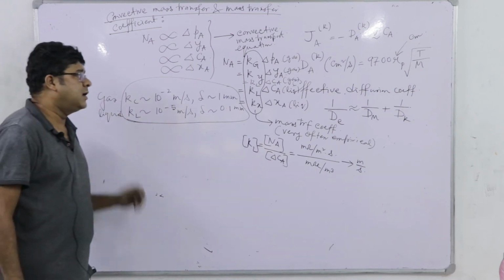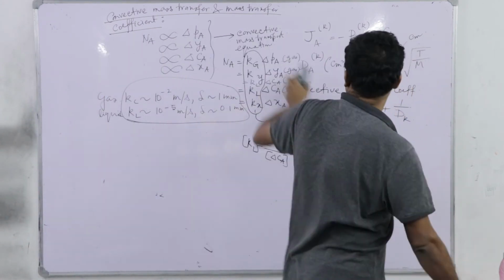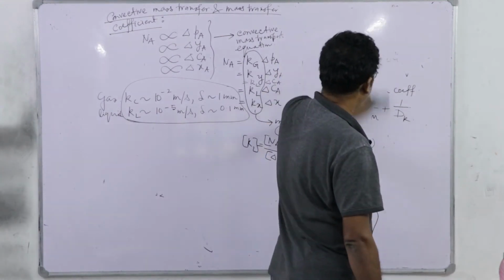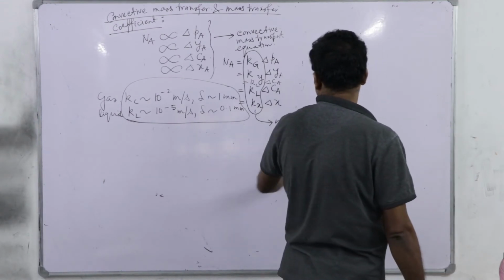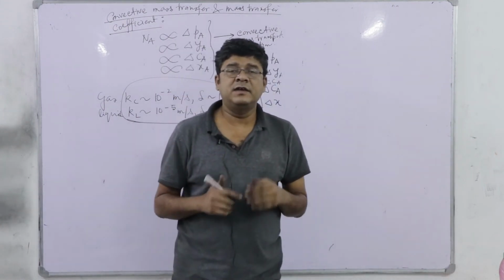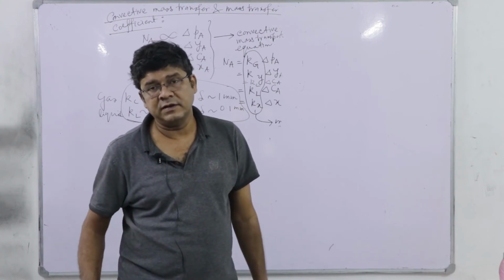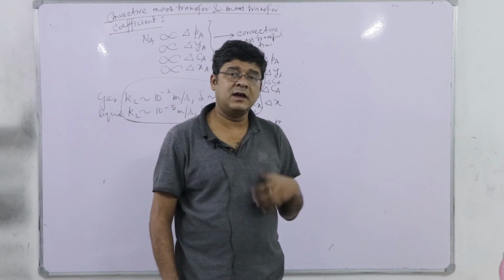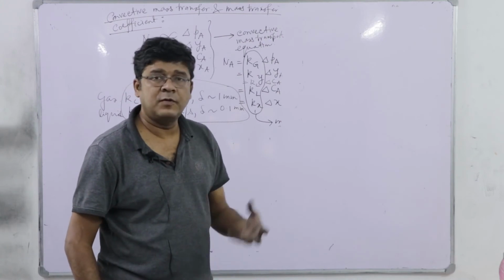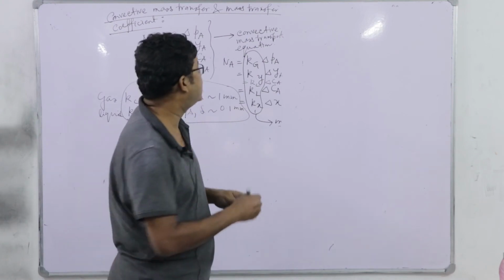So next, very similar to convective heat transfer, because we are incorporating empiricity to calculate these K values, first we will introduce the different dimensionless groups. Here, the Nusselt number we have described, which incorporates the heat transfer coefficient, and we will just replace the Nusselt number by the equivalent dimensionless group incorporating the mass transfer coefficient, and that we refer to as the Sherwood number.